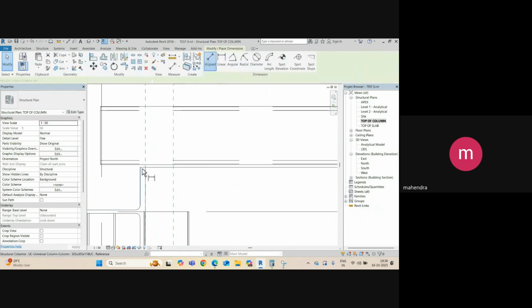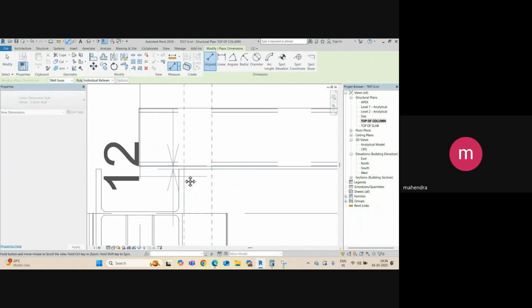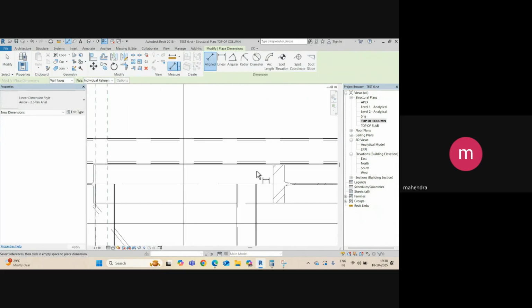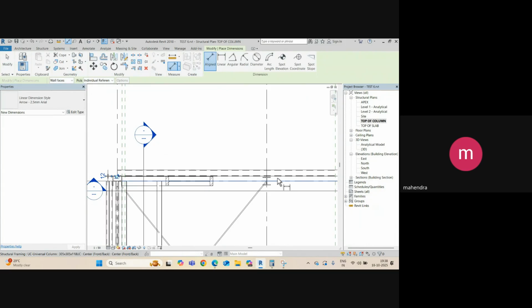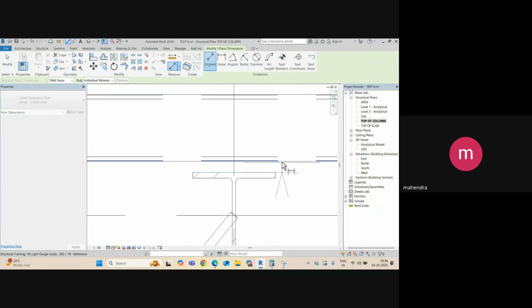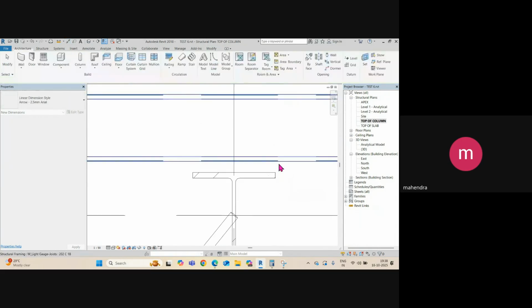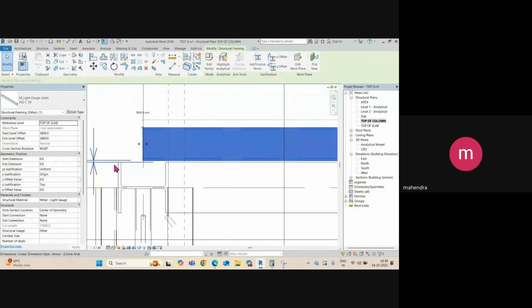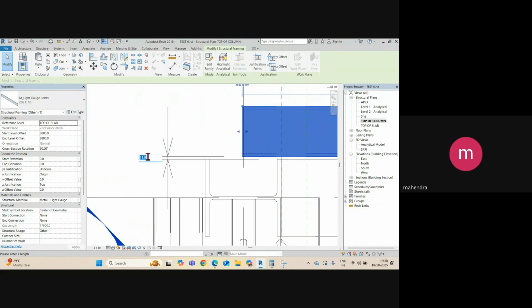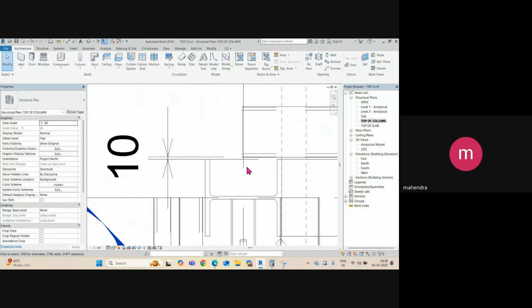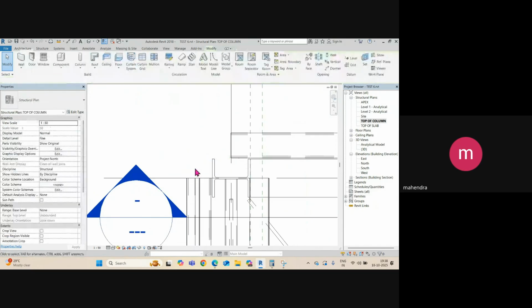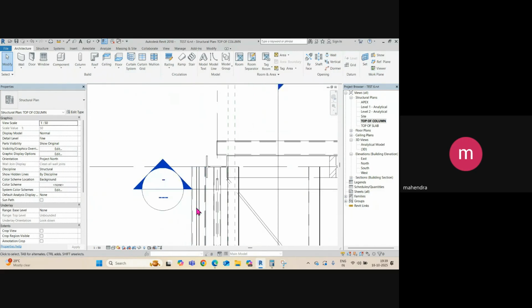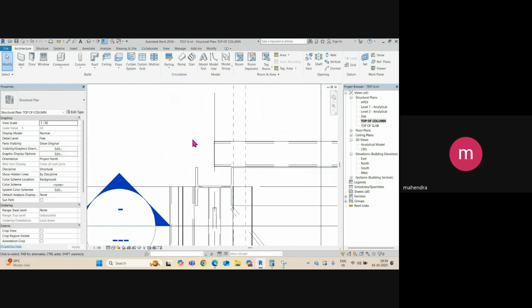So if I measure this, okay, so this is 12 mm. And if I go to here to the wind column, so here our wind column. Okay, so you can see this is 35 mm, but you need to go with that as per this condition. So I will just make it 10 mm this. Okay, and then after that you need to trim this and this member. Okay, so all in this direction side guards should be stopped at this level.